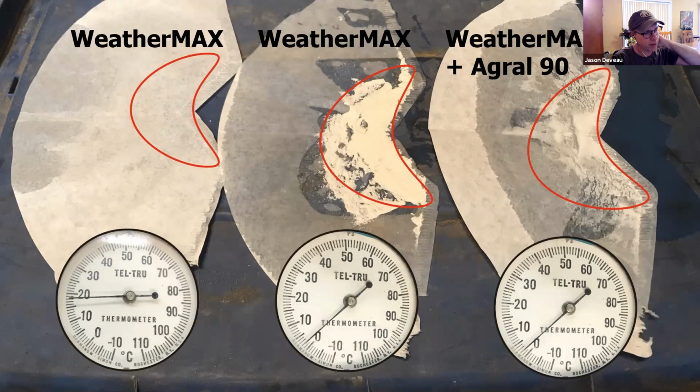At about 20 degrees Celsius, a nice warm day, WeatherMax completely dissolved. In the middle, WeatherMax at just above 0, not so much. And then one of the registrants said, well, of course not. WeatherMax needs Agral 90, a surfactant. That needs to go in there. You silly buggers, you should have used it. We said, okay. So we did. And there it is on the right. Better, but nothing I would be happy to see stuck in my filters. Water or carrier temperature matters.